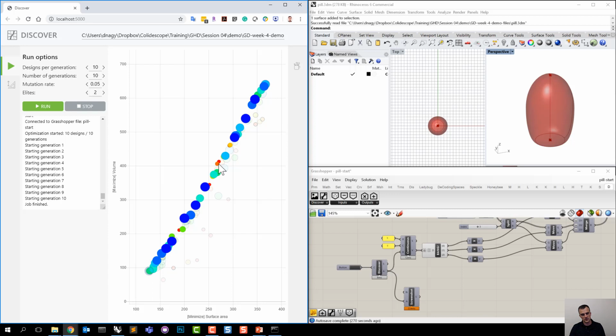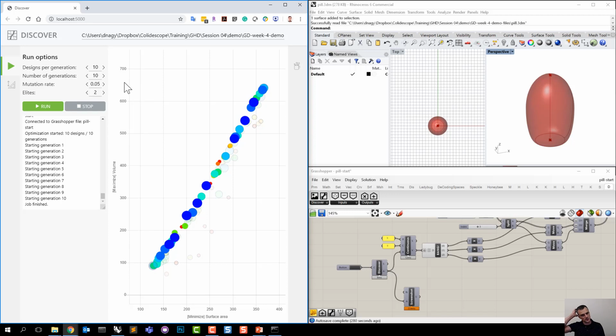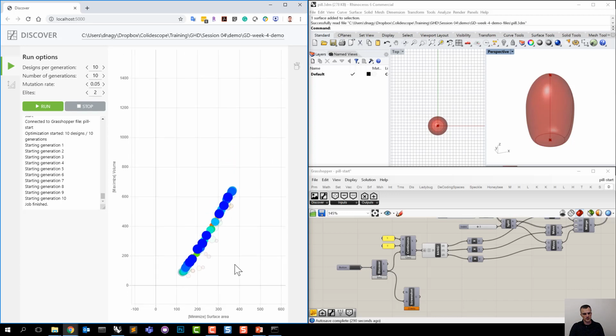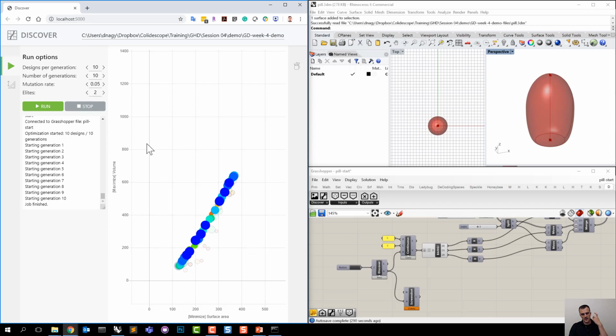as the algorithm is pushing into the space and finding the best trade-offs to these two objectives. And the way you can think about this is you can look at your objectives and you can imagine this kind of imaginary point, which we call the utopia point, which would, in an ideal world, optimize both of the objectives at once. So for example, we can imagine a design which maybe has 0 surface area, right? So infinitely small surface area with a huge volume, and that would be somewhere over here, right? Now, in the physical reality of this design space, that's not possible, but what the algorithm is doing is trying to push these designs closer and closer to that utopia point. So if you look at a more complex multi-objective model, you actually see this sort of barrier or this front of good designs sort of getting closer and closer to that utopia point.